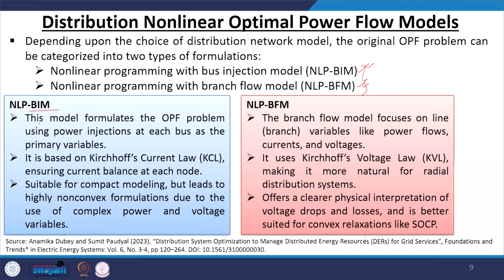The bus injection model formulates the OPF problem using power injections at each bus as the primary variables. If you have a bus like this, it will take Pi and Qi as the variables. It is based on Kirchhoff's current law, what we already derived when we derived the bus injection model. It is suitable for compact modeling, but leads to a highly non-convex formulation due to the use of complex power and voltage variables.